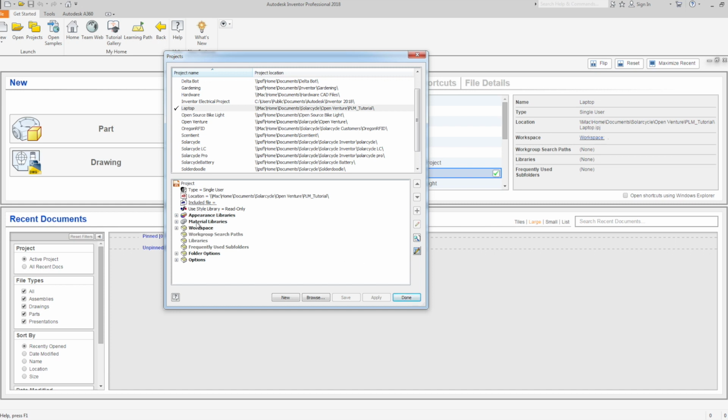And here also below, once you create the project, you can actually add another library. In the libraries is where I would put my hardware folder that I was talking about earlier. So your hardware folder is going to be in a separate folder, and you'll just add that path to the libraries here.